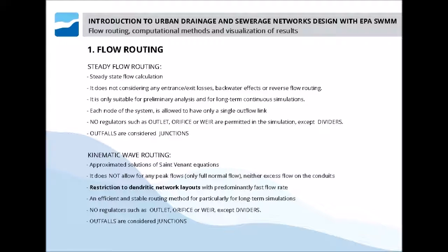Another more developed computational method, allowing for a non-steady flow routing, is the kinematic wave routing. Calculations are based on Saint Venant's equations, though some of the equation terms are not considered. This method will take full consideration of flow peaks and overflooding. It can only evaluate dendritic and rapid-flowing networks that are not overflooded. It is a very fast calculation methodology, and it is more stable. In fact, the simplified formulas make the whole process much faster, and results converge in a clearer way.